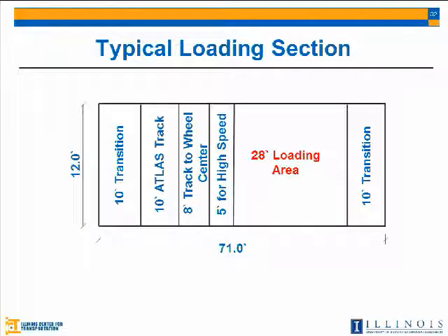In your project, you have two different designs, N90 and N70. Yes. Between the two designs, you also have one mixture with natural sand. Yes. And also you have different compaction numbers, so you have different binder content as well. Yes. In that case, if you have different types of aggregate, mainly the bonding between the aggregate and binder will have some moisture damage on the different entities, right?